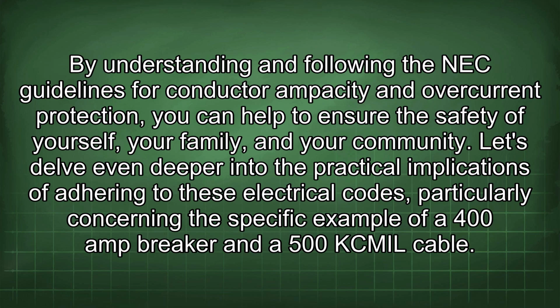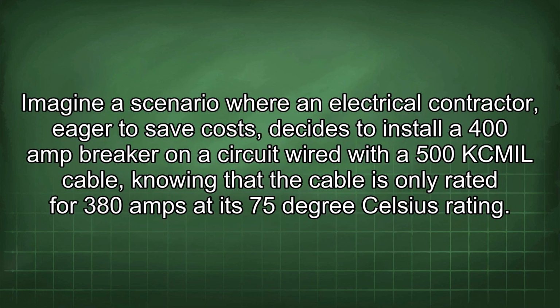Let's delve even deeper into the practical implications of adhering to these electrical codes, particularly concerning the specific example of a 400 amp breaker and a 500 kcmil cable. Imagine a scenario where an electrical contractor, eager to save costs, decides to install a 400 amp breaker on a circuit wired with a 500 kcmil cable, knowing that the cable is only rated for 380 amps at its 75 degrees